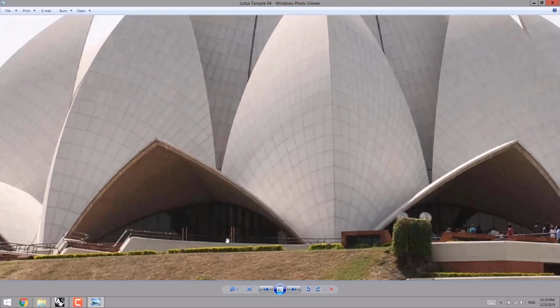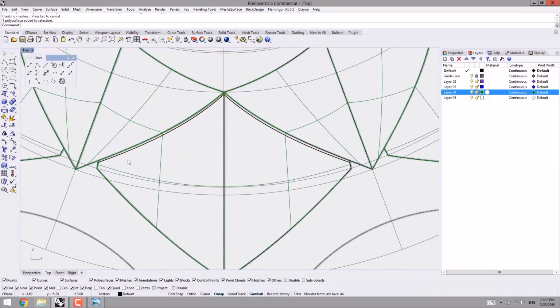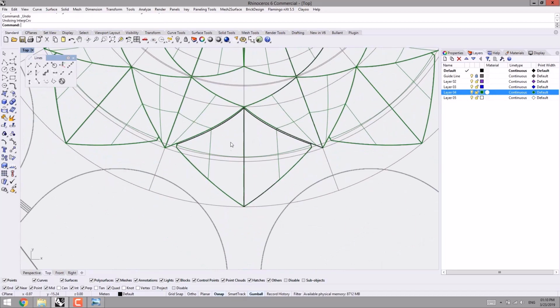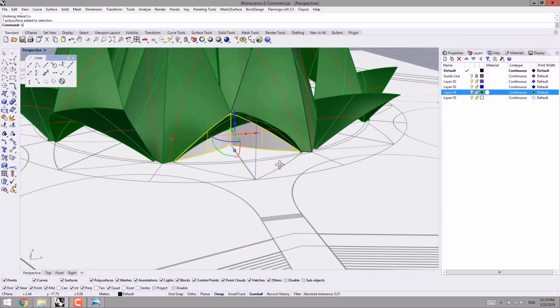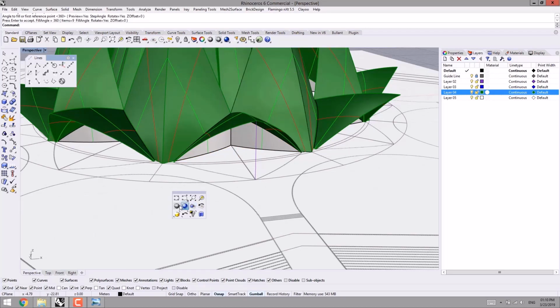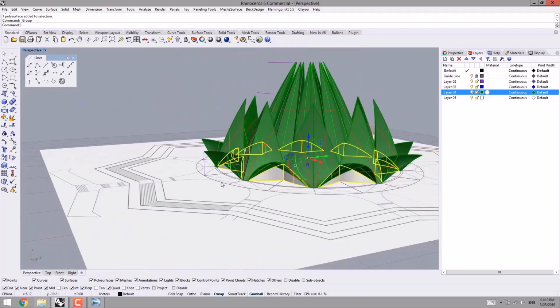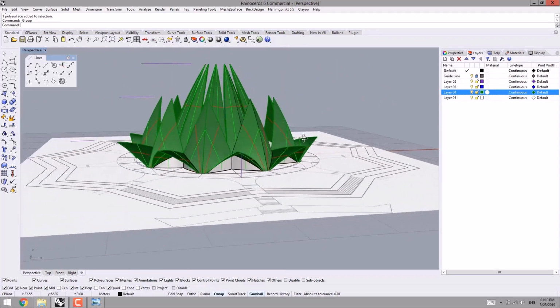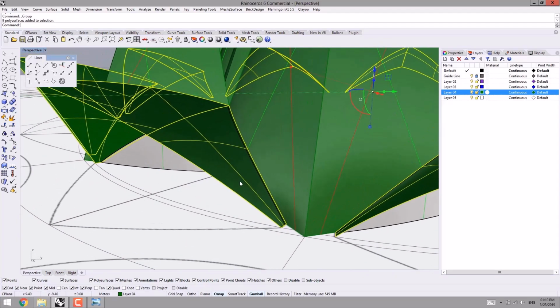And if you want to reduce the sharpness of the curve, we can sketch our line straightly like this. But for now, this is satisfying, and then I select it. Array polar, the center of the array, 9 as items. Well done. Then I select the last created objects. Following that, I press Ctrl G to group them. So till now we have created our surfaces.